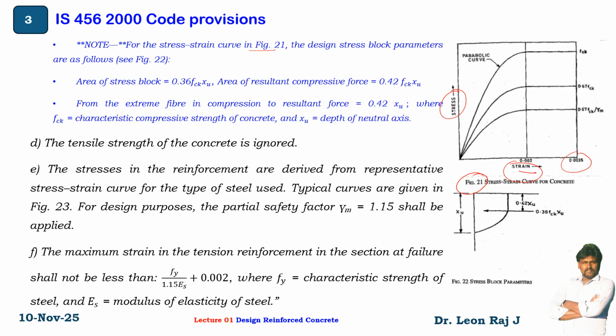Up to 0.002 the curve is parabolic, and the stress is constant in the region between 0.002 and 0.0035.